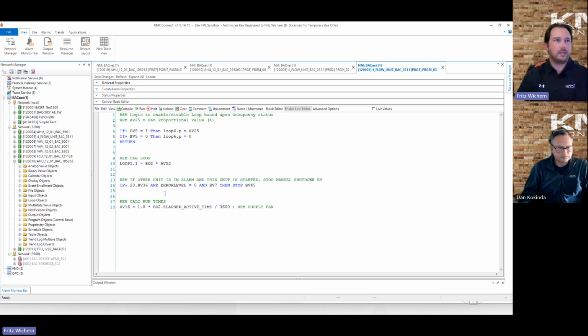Another step up, one thing I hadn't thought of that I'm glad you mentioned earlier too was the error level, and making sure that the data you're going out to pull is actually valid data, and not just going to give you some screwy numbers and not work the way you want it to. Yeah, if you have a power outage or something like that, it takes a little bit for the network to stabilize, and you'll actually get a NaN back when you do your reads, and you may get unintended code execution if you don't account for that.